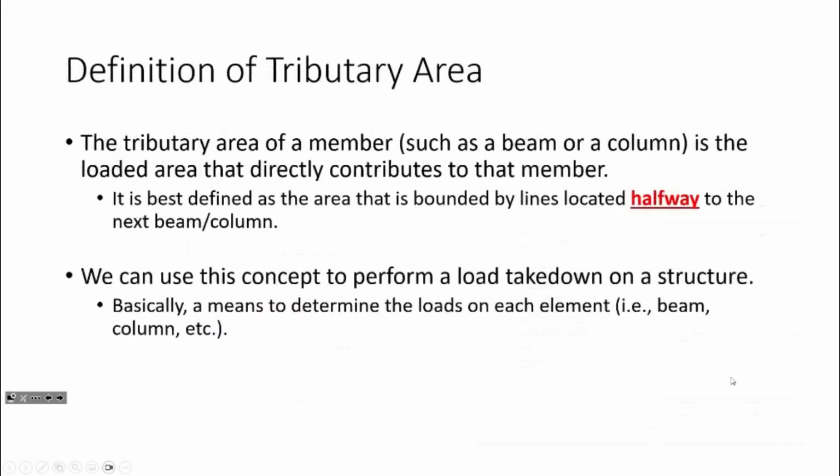Okay, so I just wanted to have a little bit of discussion about loads and where they come from. The one load that I didn't mention actually is environmental loads. I said where they are. So we have to design buildings also to withstand wind and snow, and those are largely a function of where they are. So for example, it's not terribly difficult to go to a given map and find, based on where we are, Huntington, West Virginia, what the ground snow load is. Around here it's going to be about 20 pounds per square foot.